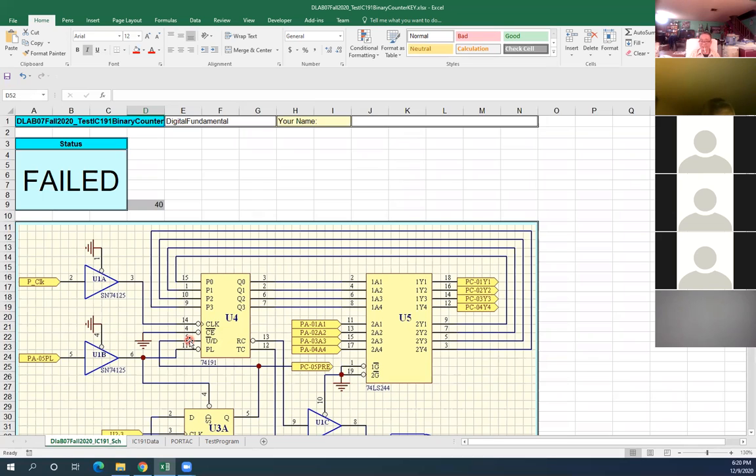But on this circuitry I routed, that means it's counting all the time. So that's always 0. The thing is, we routed it to ground, so it's always 0, so it's always counting. Whether you want to count up or count down doesn't matter. So that's the enable. It allows the counter to count the number, up or down, doesn't matter.